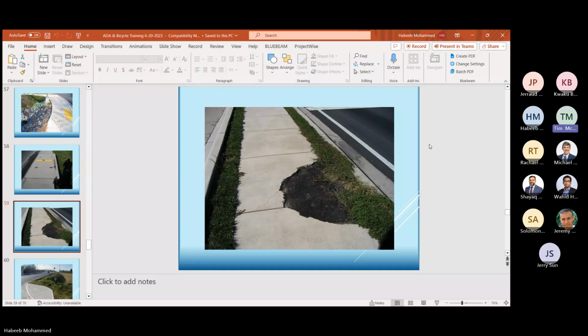I'm talking about an existing roadway where the longitudinal grade of the road and the sidewalk is like 10%. And if you try to insert one of these handicap ramps where you've got that 12-to-1 slope, the roadway is already steeper. What do you do in that case? Yeah, we have to match the roadway slope basically.